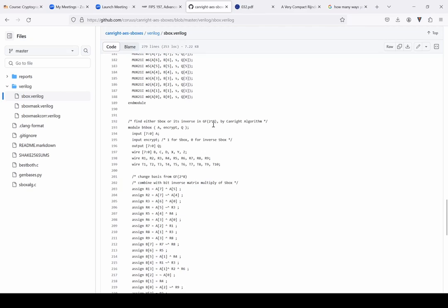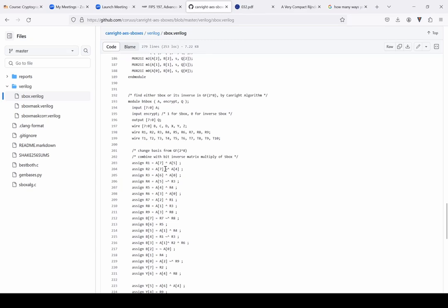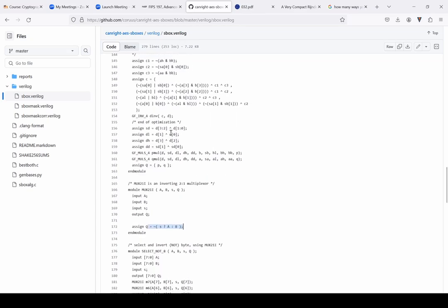And then David Canright checked almost everything, I mean, exhaustively, and then selected this implementation as the winner. Then if we look at the upper parts here, you can see that XOR and XNORs are used. You should keep in mind that I talked about the AND and NAND gates. I mean, the AND is larger than the NAND, but it's not the same for example for the XOR. XOR and XNOR usually have the same area. I mean, it doesn't matter if you use XNOR or XOR, then you don't need to use XOR and then invert the output or invert one of the inputs.